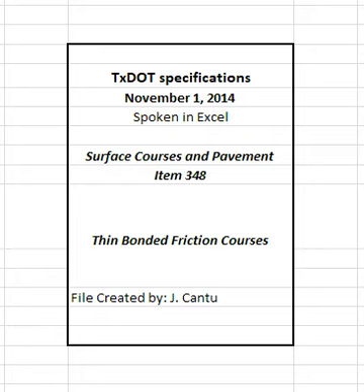2.6.2 Lime mineral filler. Add lime as mineral filler at a rate of 1% by weight of the total dry aggregate in accordance with Item 301, asphalt anti-stripping agents, unless otherwise shown on the plans or waived by the engineer based on Hamburg wheel test results. Do not add lime directly into the mixing drum of any plant where lime is removed through the exhaust stream unless the plant has a baghouse or dust collection system that reintroduces the lime into the drum.